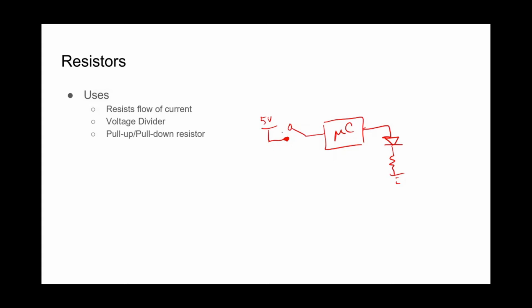So with this 5 volts here, if the button is closed, then that connection is made, and all of a sudden this reads 5 volts at this line. So if closed, then we'll call this Vin or VM, for V microcontroller or V micro. All right, if closed, then V micro equals 5 volts. But what if it's open? If it's open, then V micro isn't attached to anything.